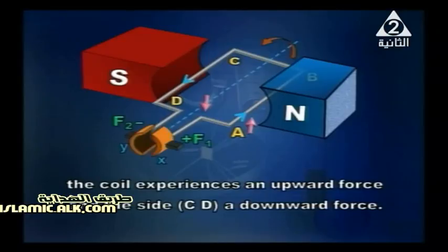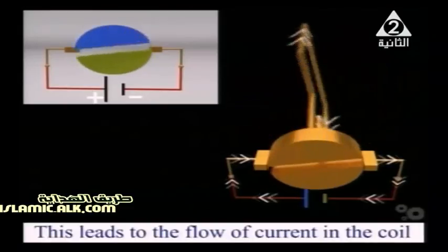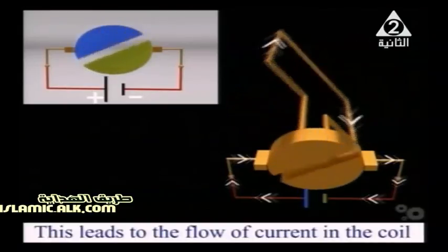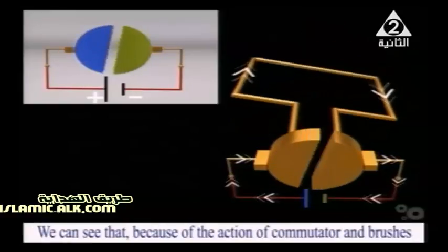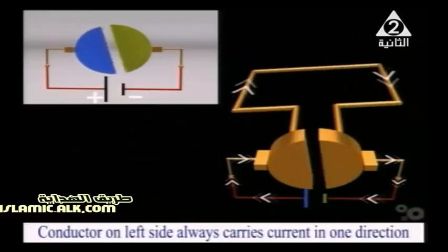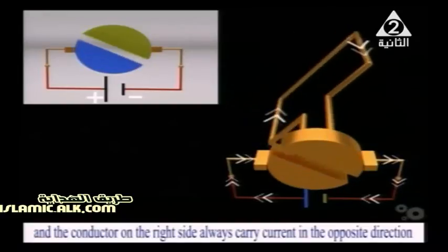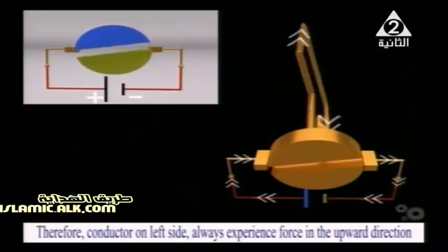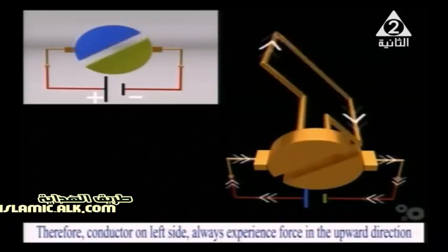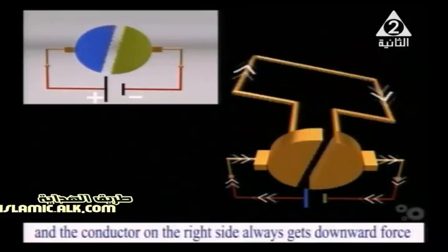These two forces form a couple. So we've got two forces equal in magnitude, opposite in direction, but parallel. These two forces, as I said, form a couple which causes the coil to rotate until it reaches the vertical position. When it reaches the vertical position, it is supposed to stop. But because of its inertia, it overshoots this position.